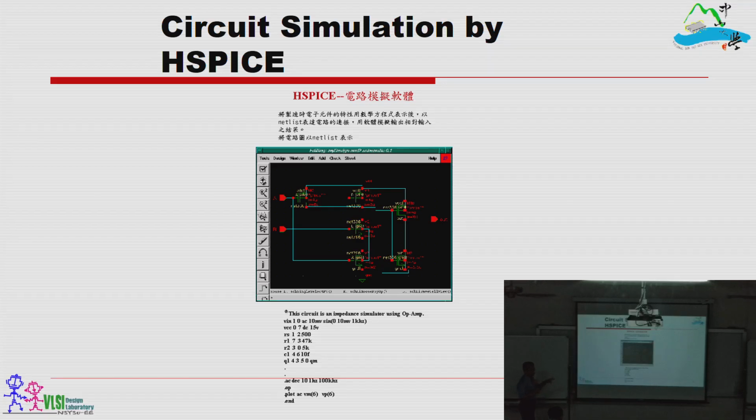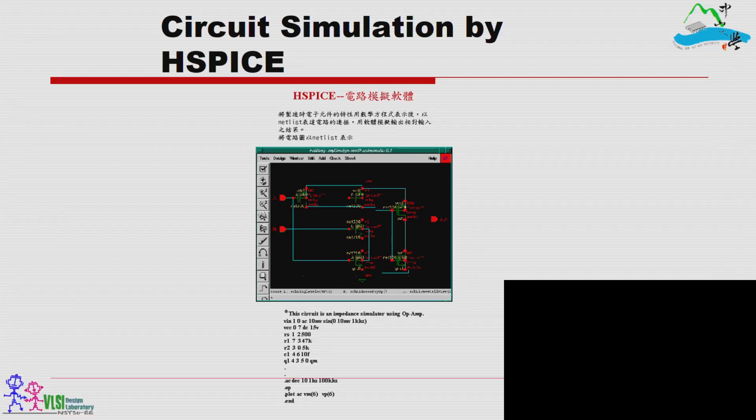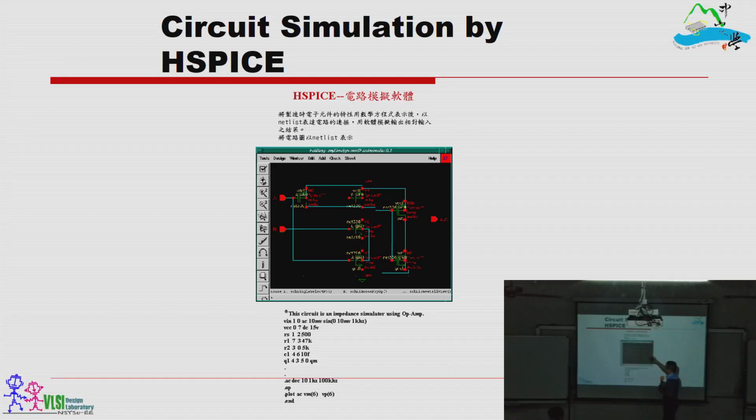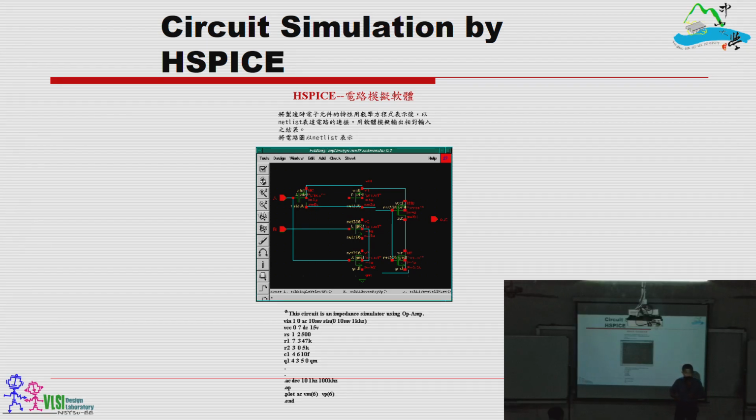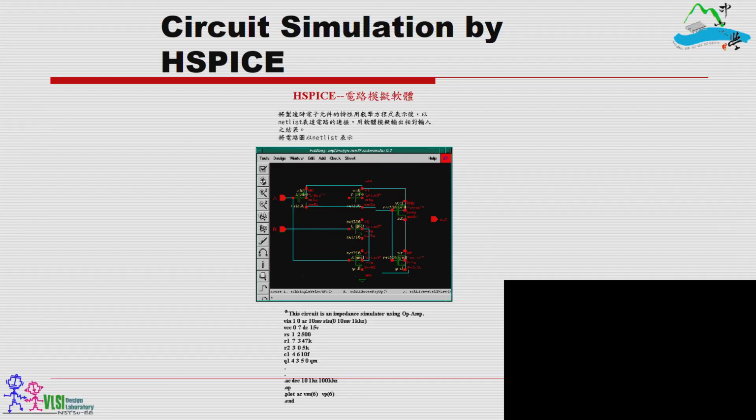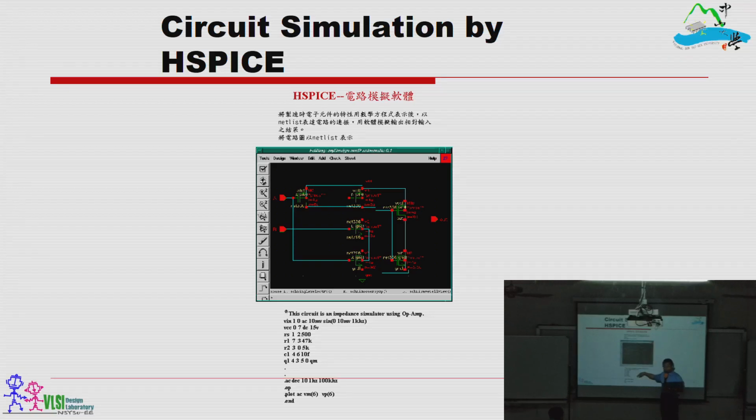This is the thing that the students will learn, and you should learn in this course. This is called Virtuoso. It's a Cadence tool. And here, you have a big window. Then the TAs will teach you how to call the transistor and tune the size, and then do the connections on the wiring between the transistors to make it work. And of course, you have input pins and output pins. Then after you finish the design in this graphic window, you can dump it into the SPICE code. So you don't have to write SPICE code by yourself.